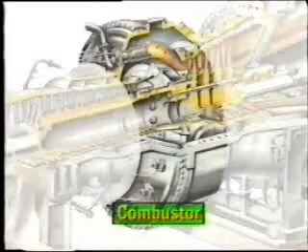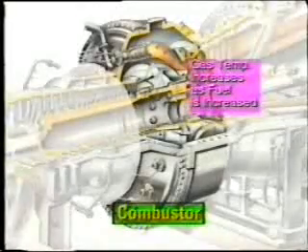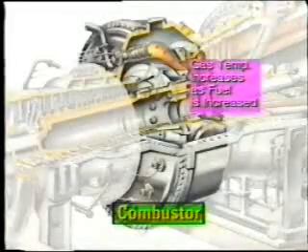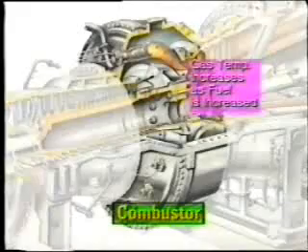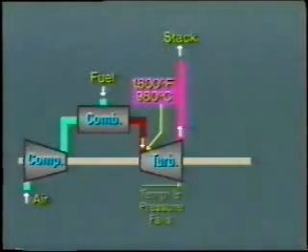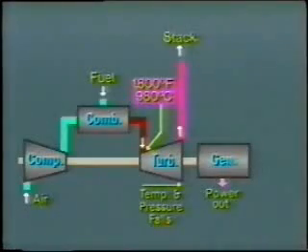Obviously, the temperature of gas entering the turbine increases when the amount of fuel supplied to the turbine is increased to accommodate a load increase. As the gas passes through the turbine, the temperature and pressure fall as energy is given up to the turbine to perform mechanical work. The turbine shaft is coupled to drive a load such as an electric generator.